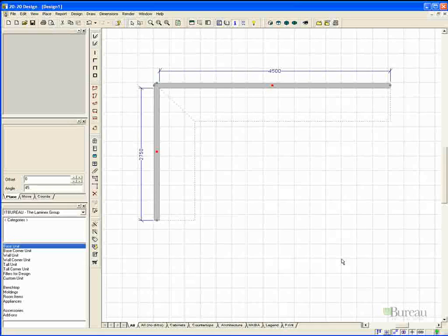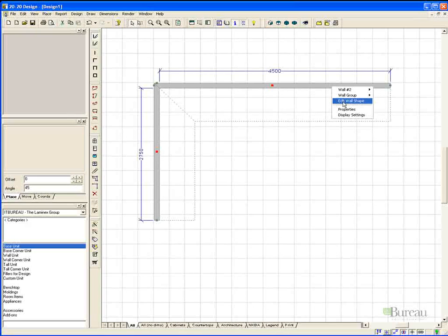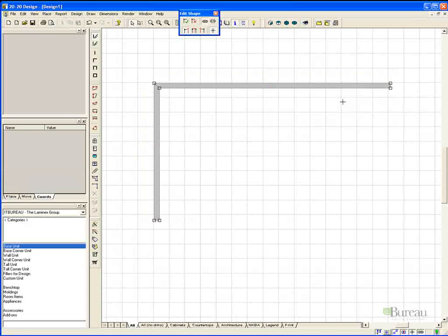We normally extend the length of this wall so that we can place the breakfast bar in accurately, because quite often there may be cabinets on either side. To do this, we will simply add a wall. Right mouse button, click over it and choose Edit Wall Shape. When you choose Edit Wall Shape, you will notice that the solid lines will become clear. We can now right mouse button click approximately 1 mm adjacent to the wall and choose Add.